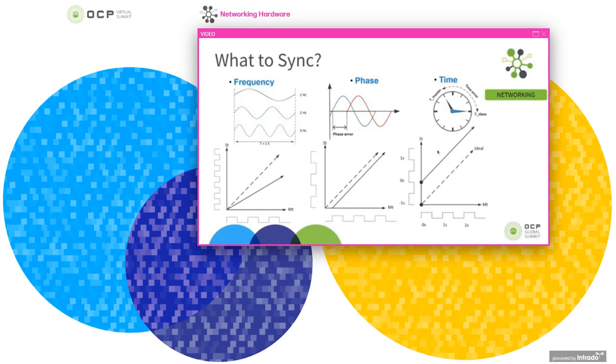And for the time, you can see the minimum unit here is seconds, because it is a relatively long range in timing. So it is much easier to deal with, maybe through I2C system or SMBus. So here, I don't think time synchronization will be a problem in our topic. The major targets are frequency sync and phase sync. Here we aim to deal with frequency sync through SyncE and phase through 1588. We will introduce them on the next page.